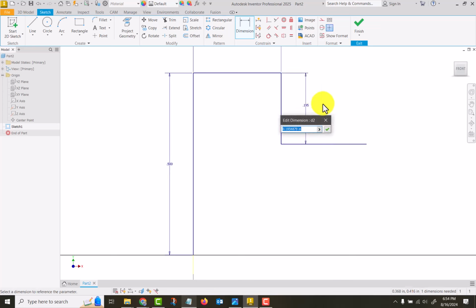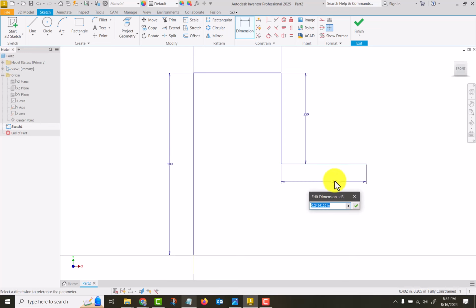It just depends on what your object is and what the shape of it is as to which is easiest. All right, so now if I want to come back in and do another line, I'll come back here and I get a green snap. It's going to put a coincident constraint so that the end of the line is selected there.